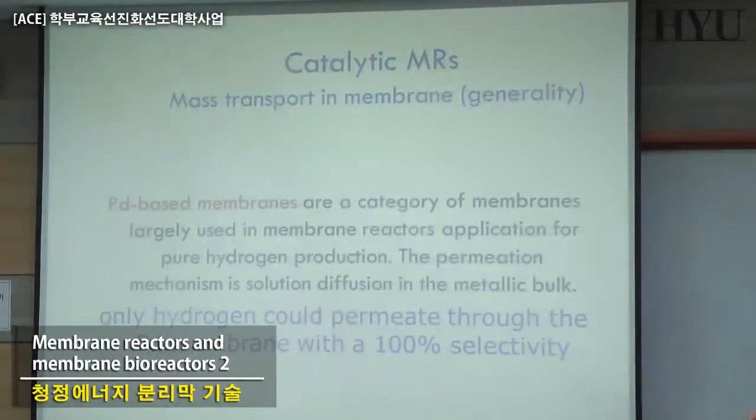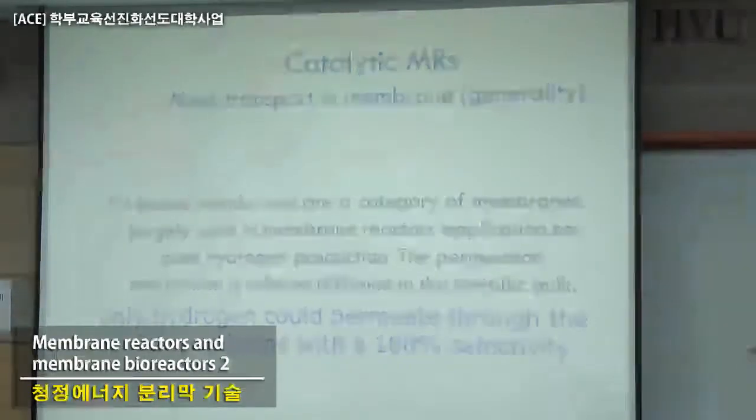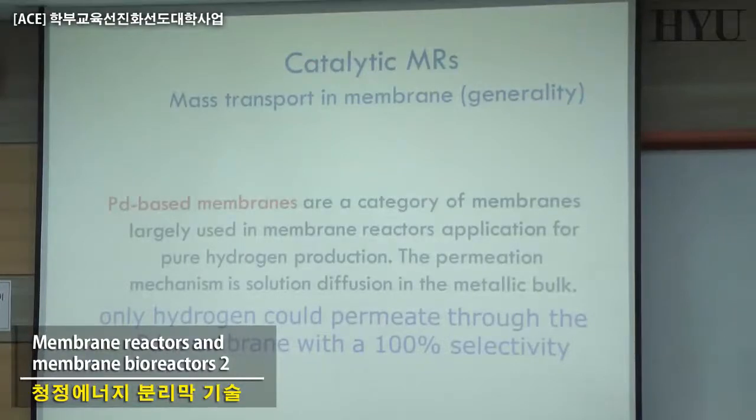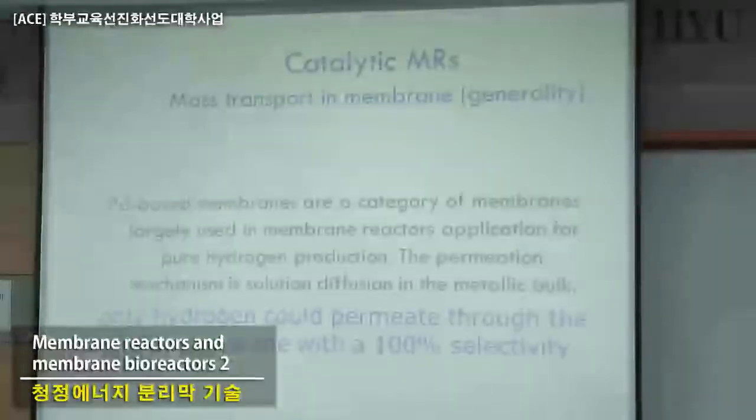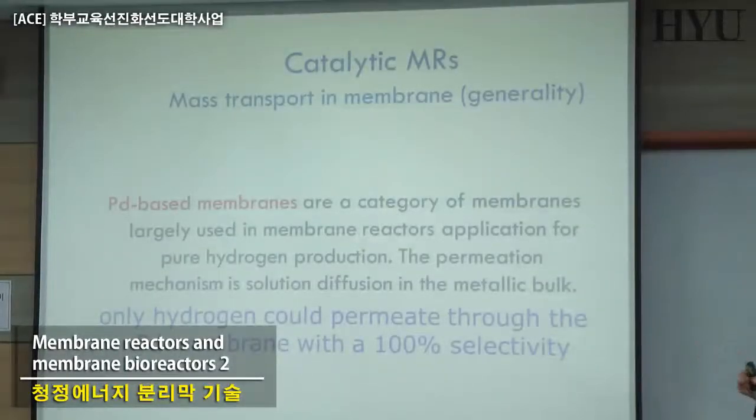This is valid for the traditional porous membranes, viscous flow, porous flow. Remember that we discussed last time that we can also have some other kinds of behaviors that make this kind of equation not 100% valid. We can have a surface diffusion, we can have a capillary condensation, and we can have the overlapping at the transition between Knudsen and viscous.